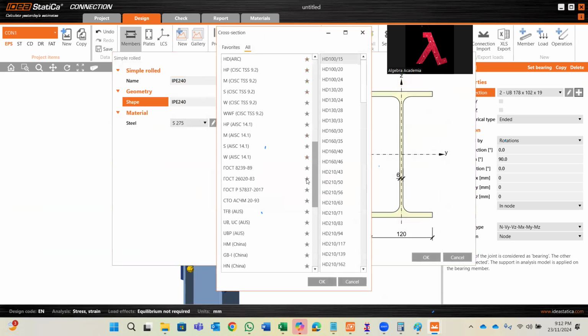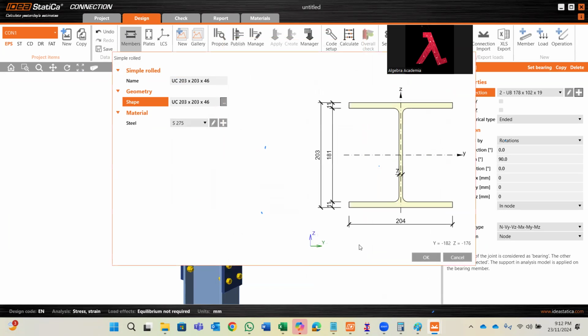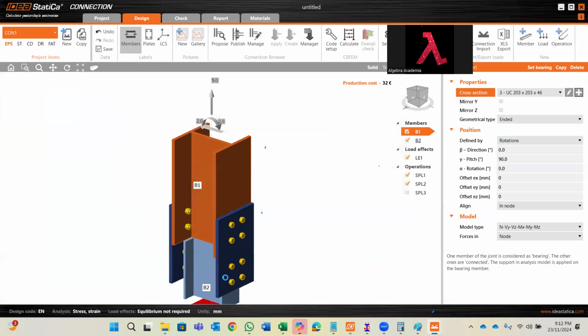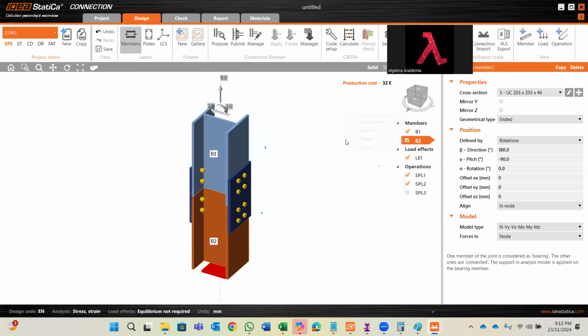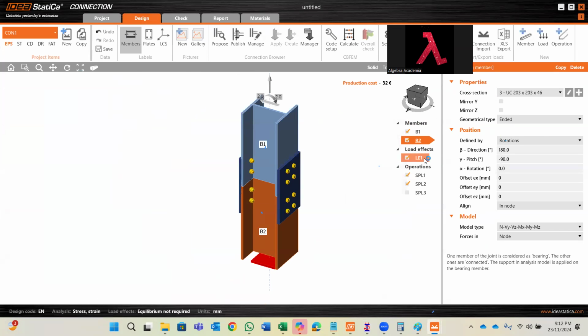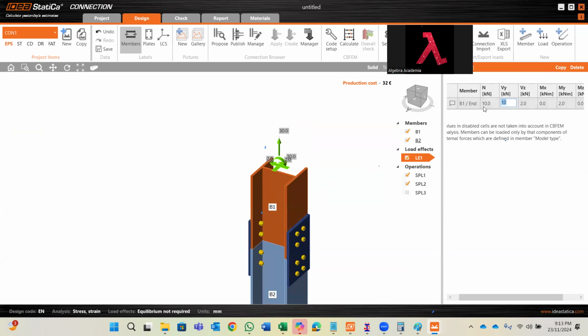You see, 46. Again, down member, 46 kg per meter. Fantastic. And now going back to the forces. Okay, the direct tension. So what you're getting is minus 10 kilonewton, which is 10 kilonewton. So here the direct tension is 10 kilonewton.